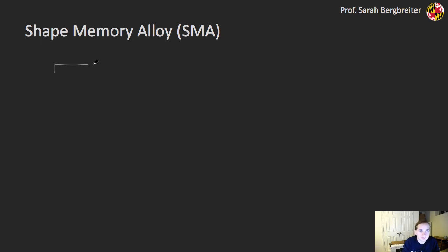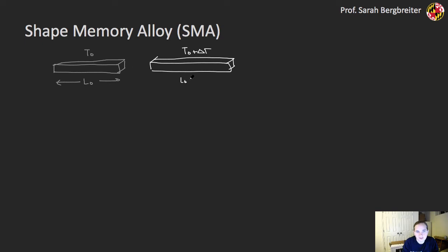And so the basic idea behind this is if I have a chunk of some material right here, and I run a current through it to heat it up, or I heat it up through some other means, I'm going to actually expand that block of material. This is obviously kind of an exaggerated drawing right here, but I'm going to have a strain based on my temperature change, where that thermal strain is equal to alpha times delta T, where alpha is a coefficient of thermal expansion, or CTE.